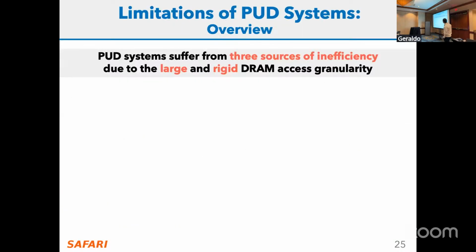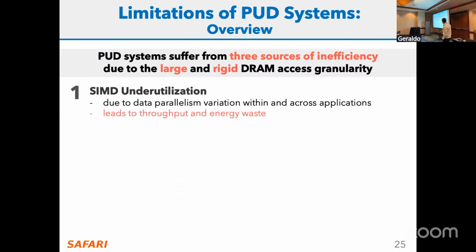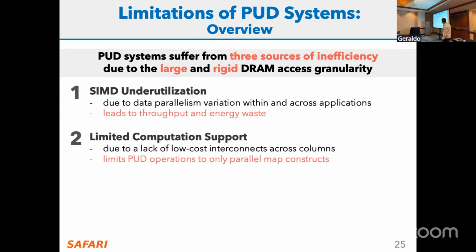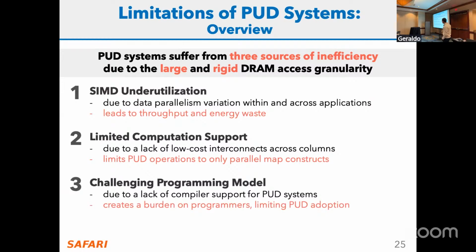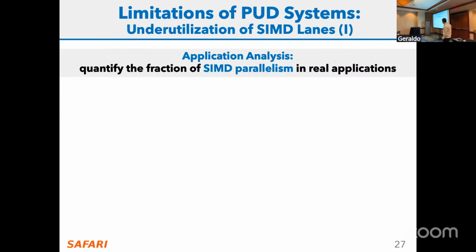Okay, all of that is very nice, but this type of SIMDRAM framework or substrate is not very efficient. And this is because of the rigid computing granularity that you have inside the DRAM subarray. So this causes 3 problems: SIMD underutilization, limited compute support, and a challenging programming model, which I'm going to briefly illustrate next.